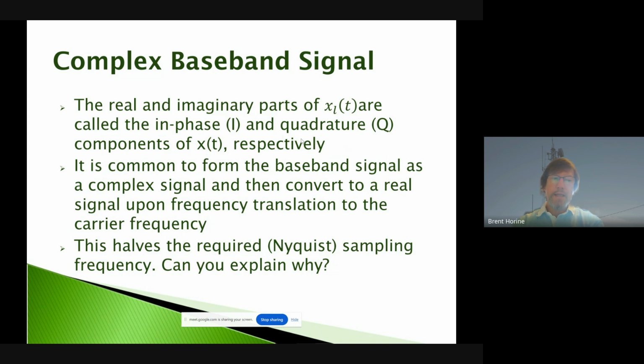So now you can pair those two up, try to build them close on the same die, the same area of the chip, so they're very well matched. And now you can sample the in phase with one part of your circuit, and the quadrature with another part, and be able to reproduce frequencies all the way up to that sample frequency, assuming you have ideal filters, right?